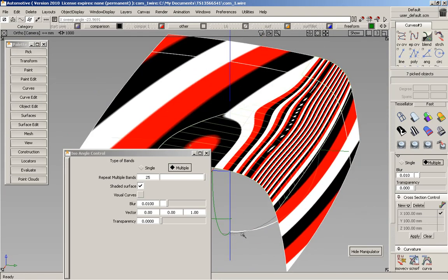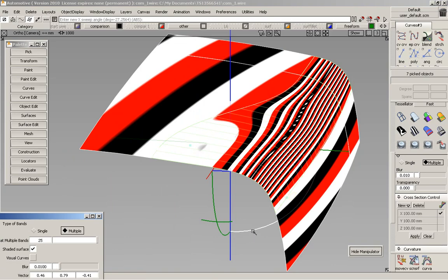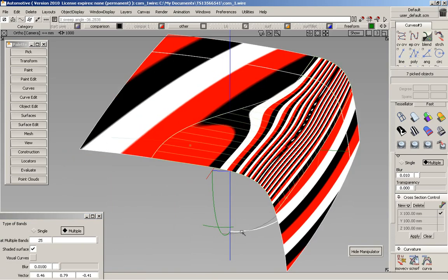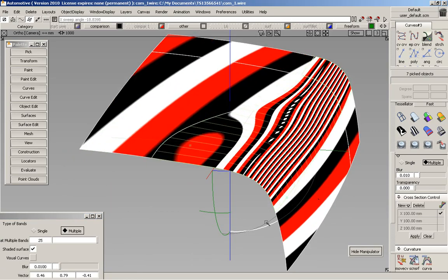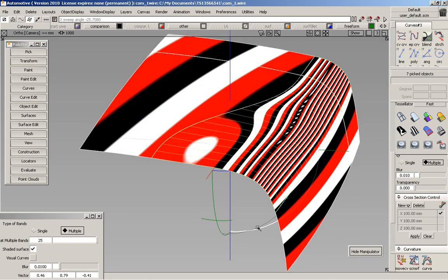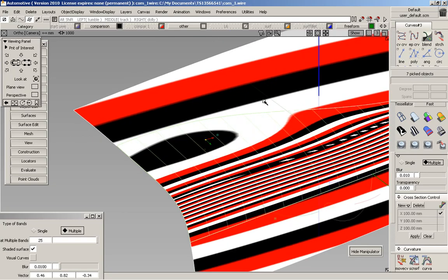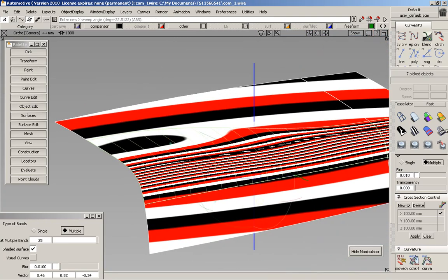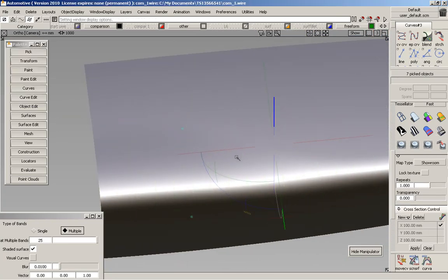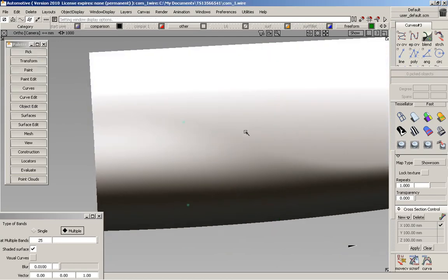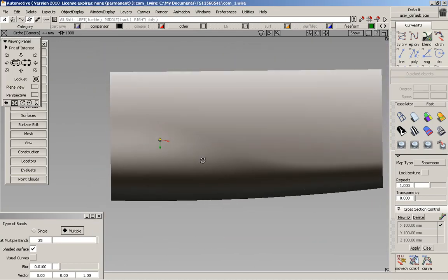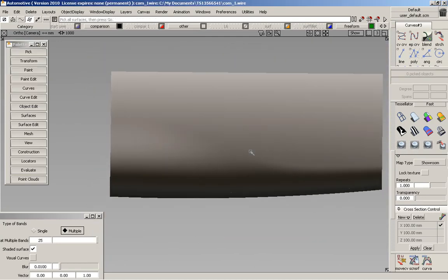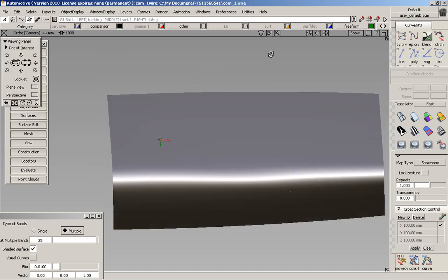You can see as I start to move this ISO angle, as the highlights start to move, there's a pit in there. So there's a little bit of a valley and a little bit of a peak from just doing a quick evaluation. Then typically I'll also take a look at how it looks with the diagnostic shade, and you can definitely see a little bump in the surface there.